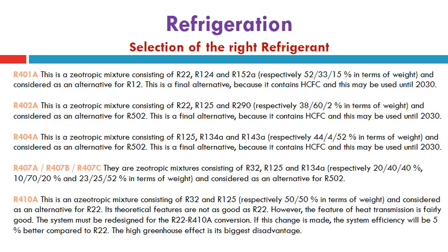This slide presents the different types of zeotropic refrigerants of the 400 family and their composition from different types of refrigerants by mass, and the basic refrigerant composition. It should be clear that this composition and these mass ratios affect the glide of the temperature inside the wet region, as has been presented for most of them, especially for R407C in its p-h diagram presented at the start of this lecture.